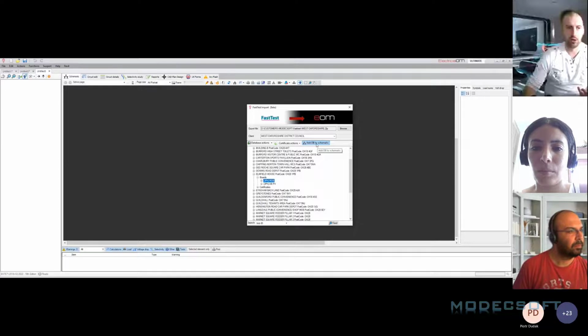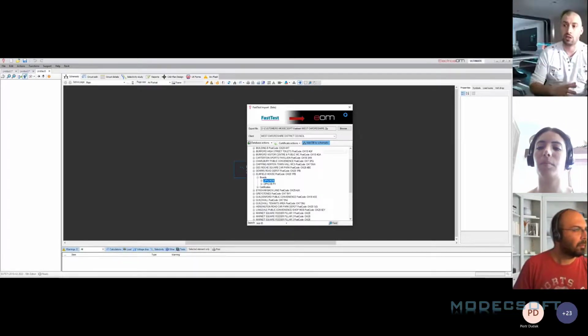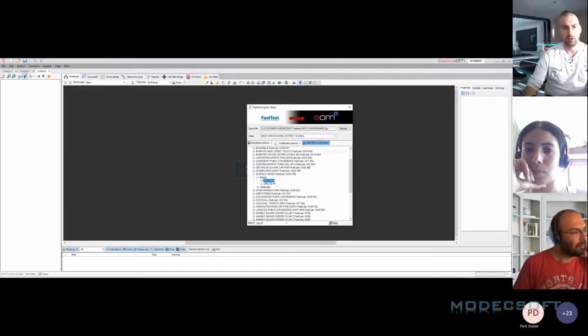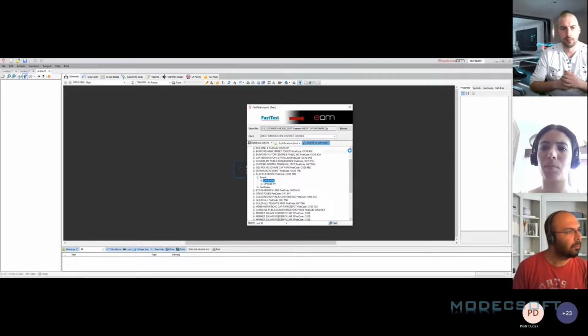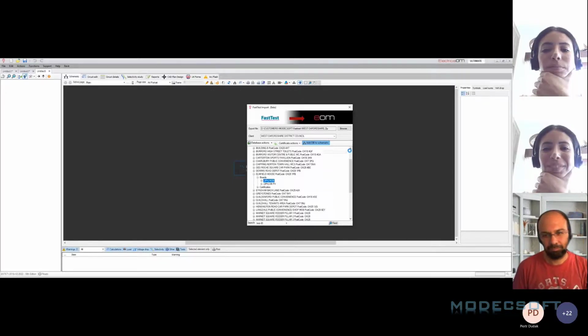So here I'm going to do add a DB to a schematic. If I select this distribution board here, it's going to search through all the Amtech files in terms of the FastTest information. From that, it's going to allow us to produce a schematic detail, a bit of a reverse engineered design from that information. You'll see that it's going to populate in here. It just takes a minute to search through all the information and data. Probably picked one that's a bit too big. It's taking a little while here too.